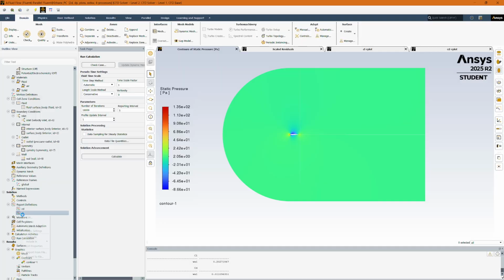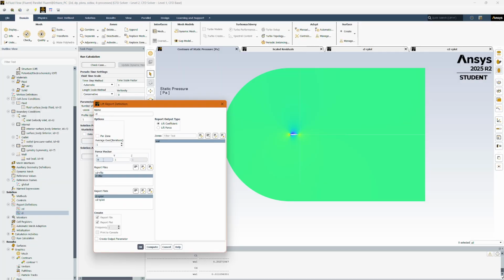Angle of attack, multiplying cosine of that and sine of that, and vice versa for lift and drag. Since our drag goes with the direction of flow and our lift goes perpendicular to that. So we get very similar values, but often the reciprocal of them. Not the reciprocal, the opposite of them. So like for this case, x and y are flipped, and x is actually negative in this case.